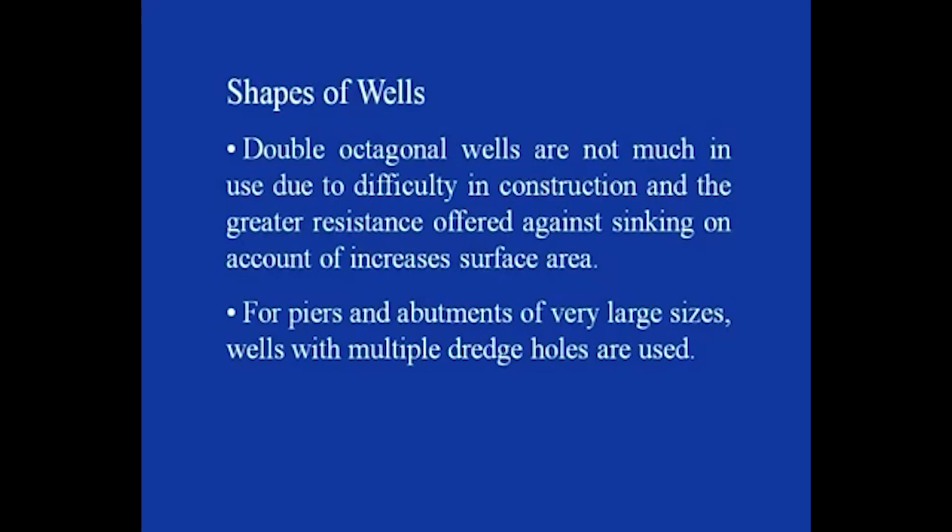These double octagonal wells are not much in use because of the difficulty in construction, because the straight edges of the well foundation cause difficulty during sinking, as they offer greater resistance on account of increased surface area.